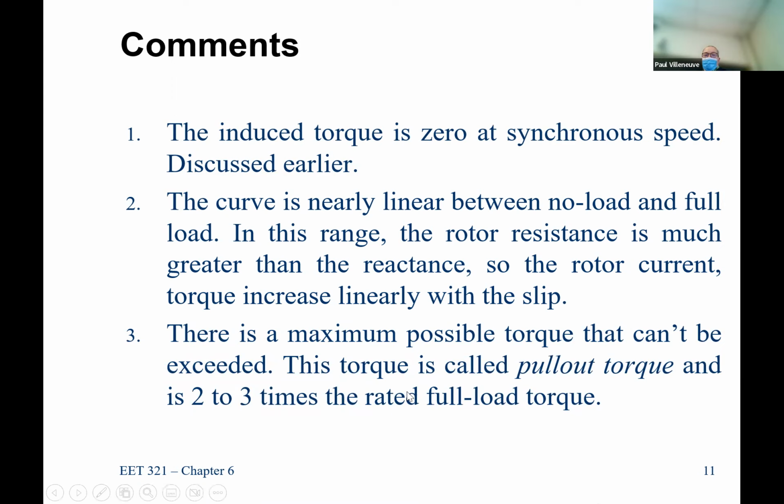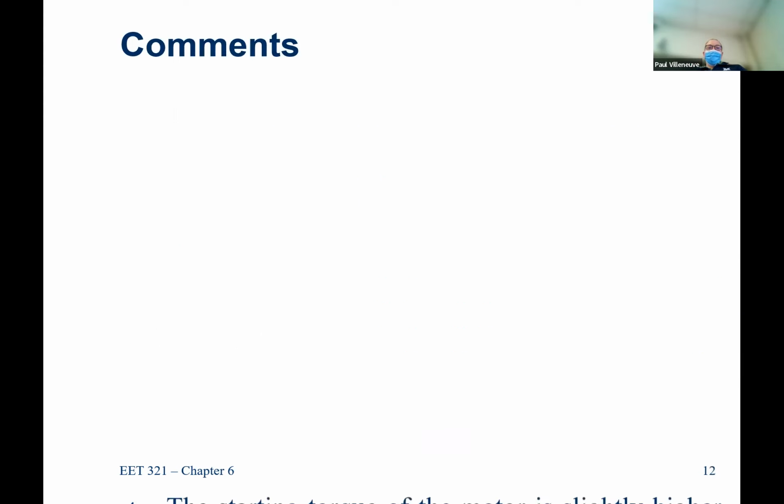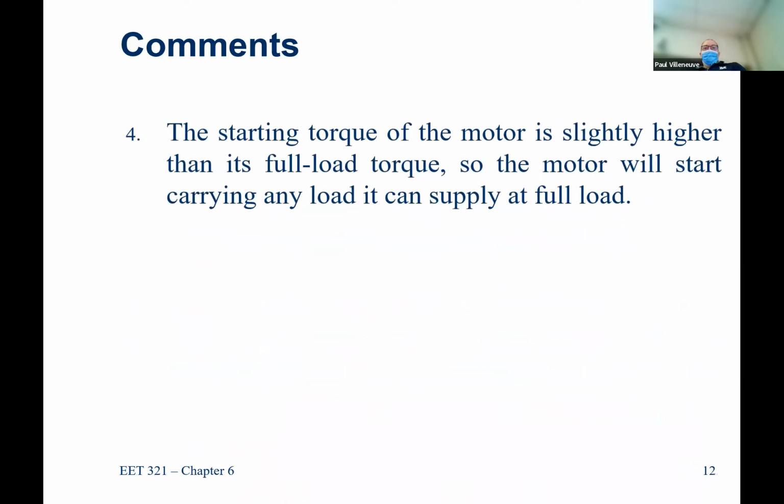So there's pull-out torque. Don't worry about the numbers. 2 to 3 times. That curve shows 450%. It really depends on a bunch of factors. So sometimes it's 2 to 3 times, sometimes it's more. We'll actually see where we can change that a little bit. So we know that the motor torque at start is higher than its full load torque. And that's a good thing.